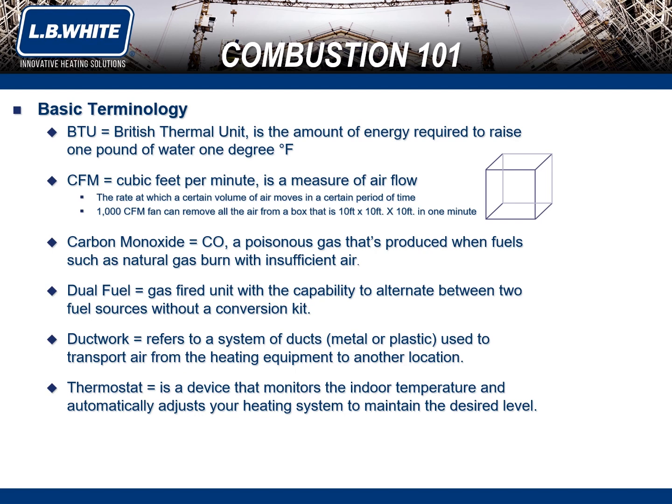Dual fuel. This refers to heaters with the capability to alternate between liquid propane gas, LP, or natural gas, NG fuel, without needing a conversion kit. For instance, a dual fuel heater can be very beneficial on a construction site where there may not be an NG source available yet. However, the heater can be set to LP first with a propane tank brought in, and once natural gas becomes available, the heater can switch to NG by means of turning the lever inside the heater to operate with NG.